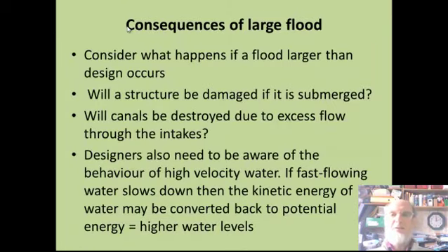So what are the consequences of having a larger than design flood? First consideration is, will the structure be damaged if it is submerged? Will canals be destroyed due to excess flow through the intakes? Also, designers need to be aware of the behaviour of high velocity water. If fast flowing water slows down, then kinetic energy of water may be converted back to potential energy and give higher water levels.